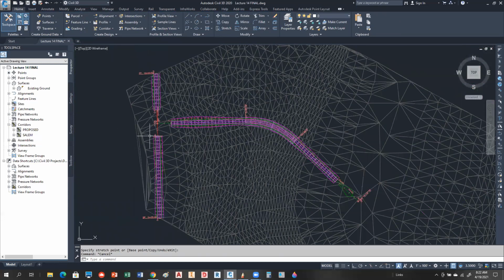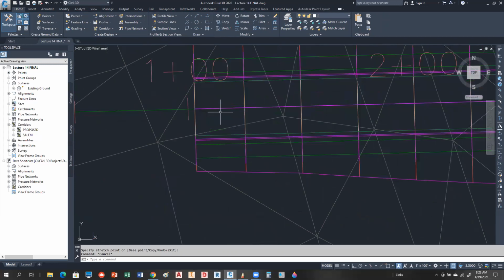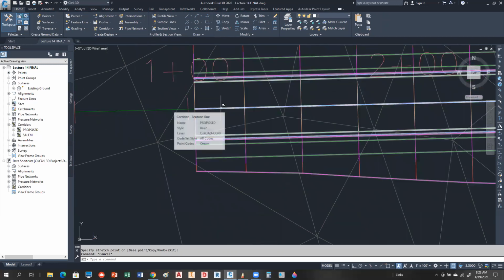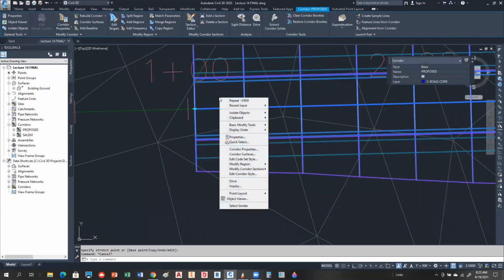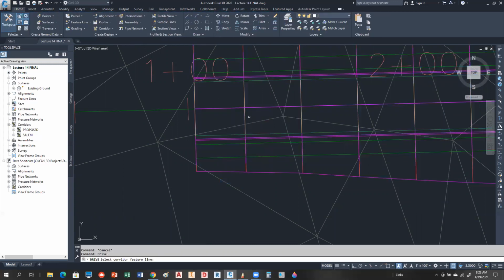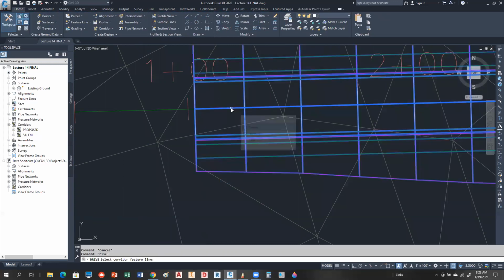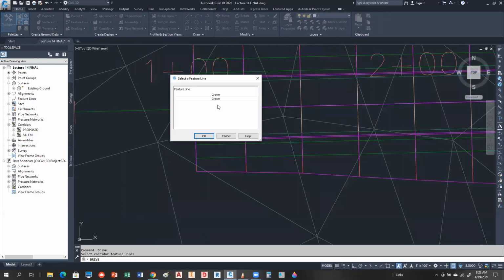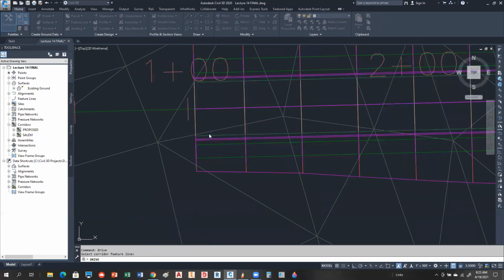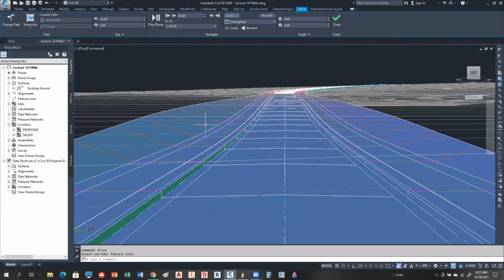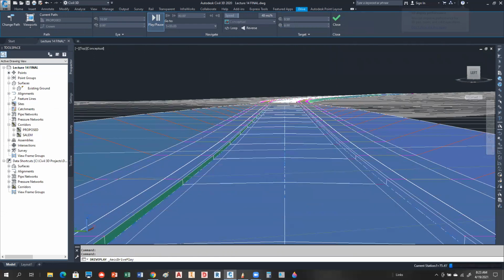Okay. What I'm going to do is a real quick drive-through on this one. I'm going to click him, right click to drive, select your corridor, and then get it crowned. Doesn't matter which crown. If you want a conceptual view, that's probably fine, but if you want a different view, you can. Go ahead and just play it through and see what it's looking like.